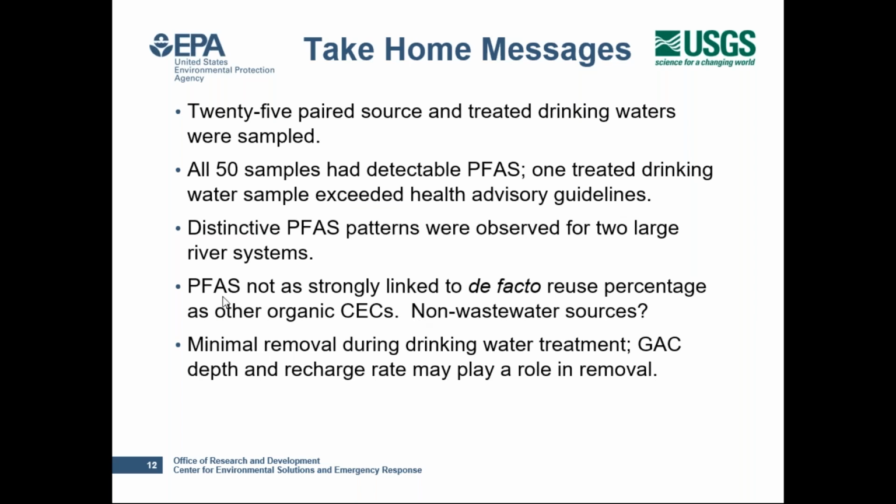And it looks like PFAS is not strongly linked to de facto reuse percentage, so perhaps there is a non-wastewater source for those, but again, we don't have enough data to be definitive on that in the study. We also saw minimal removal during drinking water treatment, but the granular activated carbon depth and recharge rate really do play a role in the removal, at least in this study.